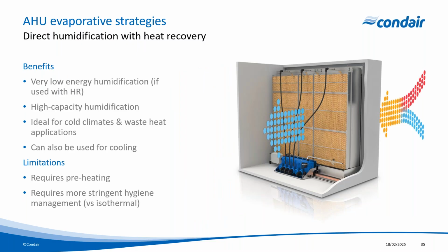So now we'll look at our final strategy, which is using evaporative technology or evaporative systems to increase the humidity without necessarily using it for the objective of cooling. So we saw earlier that when we looked at the world map, this type of humidification can be very beneficial when we've got a free air cooling system in cold regions where we've got potentially waste heat or excess heat available for reheat. So as soon as we take that cold air, heat that up to be able to supply that to data center,